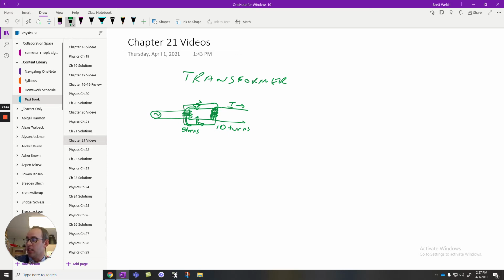That change is what allows us to induce a current and a voltage on what we call the secondary coil and produce some sort of voltage difference between these two terminals here and here. Okay? If it was constant DC power, there would be no induced current. That's really important. So let's say that we had 3 volts being supplied. If we have twice as many turns coming out, then the voltage coming out would be twice as big. So we can step the voltage up.